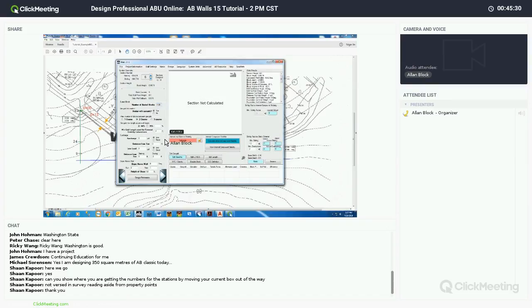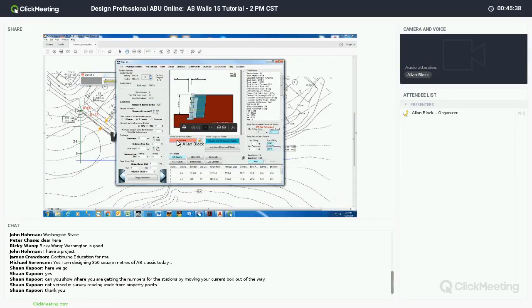All right, so at this point, I'm going to hit the calculate button, which is going to give me a flat top, no surcharge, standard wall design. When I hit that calculate button, it has applied the first layer of grid on the first course of block, also per best practices, and then it has run the external calculations, and all of our variables are viewed in the wall results box here on the left. It also gives you, towards the bottom of that box, bearing information. So if you ever have to worry about bearing, you have your values here. Our externals are viewed below with our industry minimums and our actual values in the calculations.